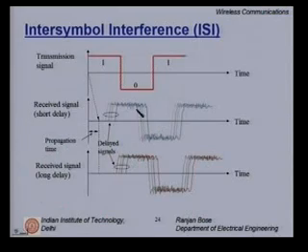In this slide, I have tried to graphically show how ISI will occur. Suppose you have this transmitted signal 101, where the x axis represents time and the y axis the amplitude. The received signal is obtained after a certain delay. Clearly there is a separation between the transmitter and the receiver, and it's noisy, and multiple copies of the same signal could be received after delay.